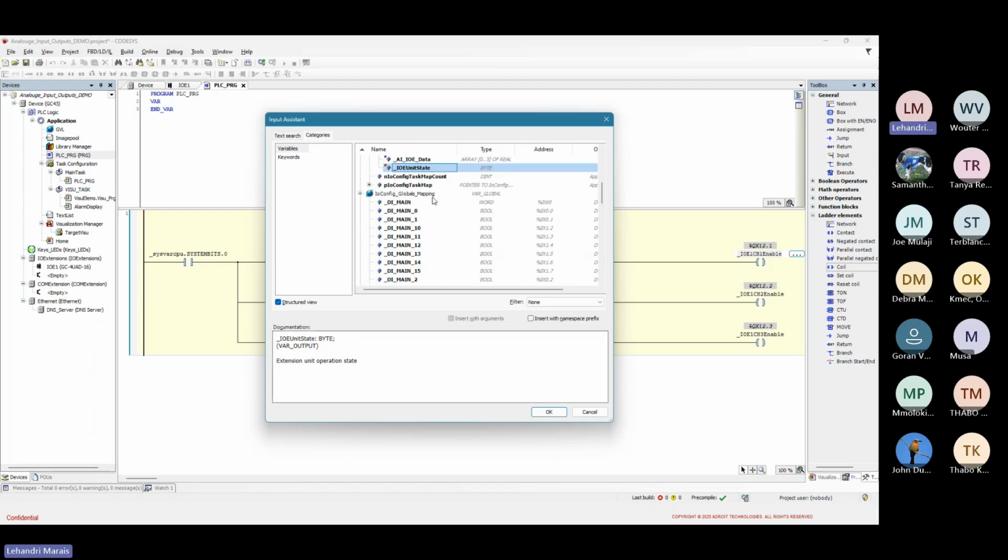Whereas the IO variables have addressing, so that's the difference you'll see here. If you look under the address column, you can see the IEC variables don't have physical addresses, they are purely symbolic variables. Whereas my channel enable and channel OK variables are assigned physical addresses.